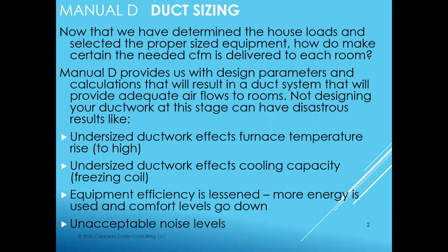Undersized ductwork, that's not going to happen. Freezing coils, those of you that have had issues with that or have dealt with that in the past, it's because the air conditioner is not getting enough air, number one, never has. And number two, they've always been twice the size. So we kind of solved that last week by getting the proper size. Efficiency absolutely is not nearly as good, not working as designed. And of course, if you've got too small a ductwork, you can actually hear the whistling, right? You hear the air moving.